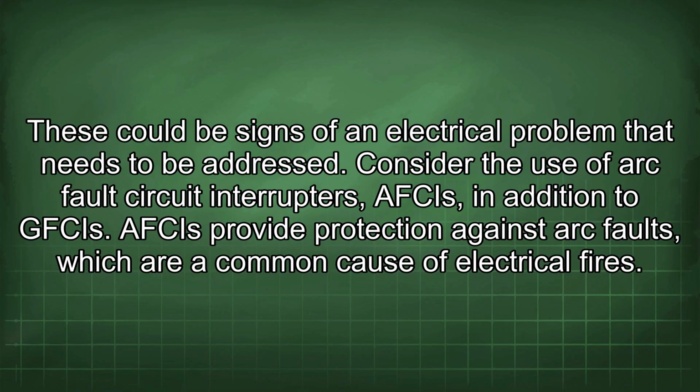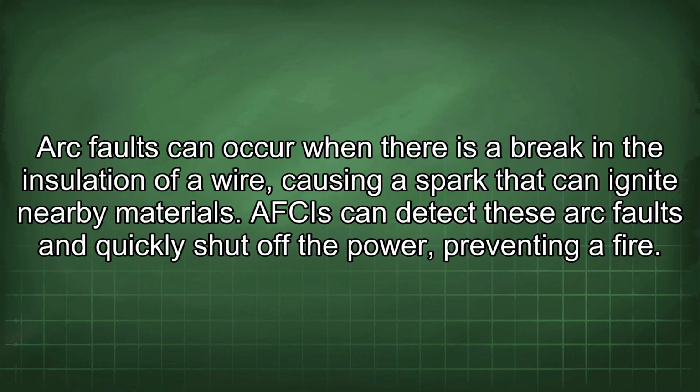Consider the use of arc fault circuit interrupters (AFCIs) in addition to GFCIs. AFCIs provide protection against arc faults, which are a common cause of electrical fires. Arc faults can occur when there is a break in the insulation of a wire, causing a spark that can ignite nearby materials. AFCIs can detect these arc faults and quickly shut off the power, preventing a fire.